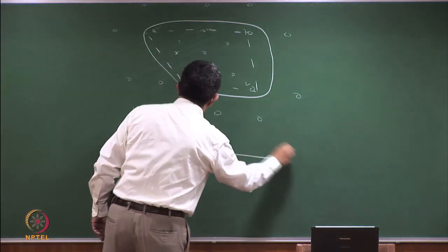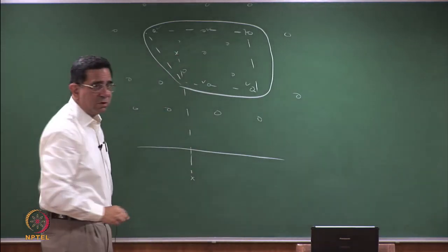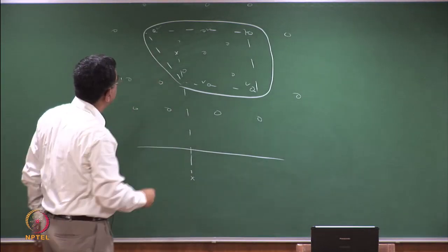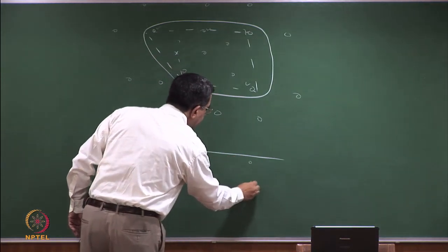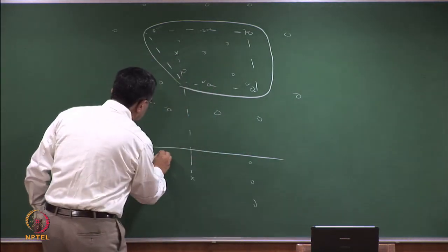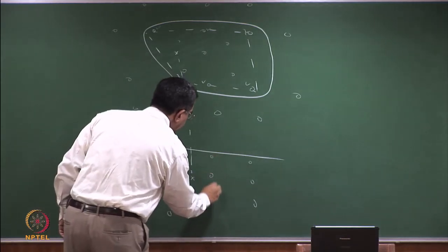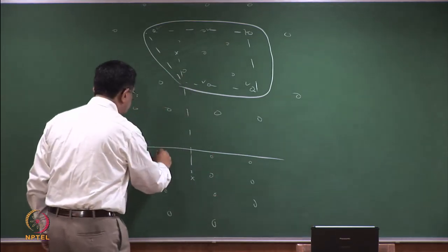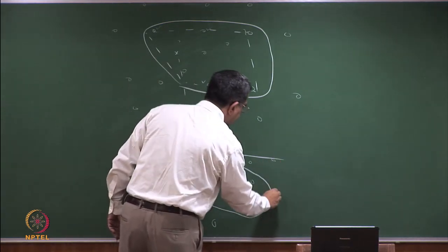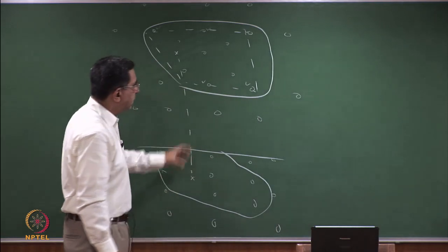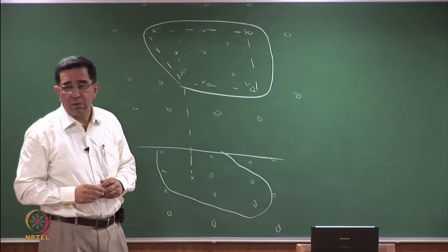Then this person had reported to you that the hand pump was picking up water from this place. So once you have identified the locations, then you might pick up samples from various depths. And then you may be able to say that my plume is something like that. So you need to be able to do detailed investigations to be able to quantify the amount of contamination.